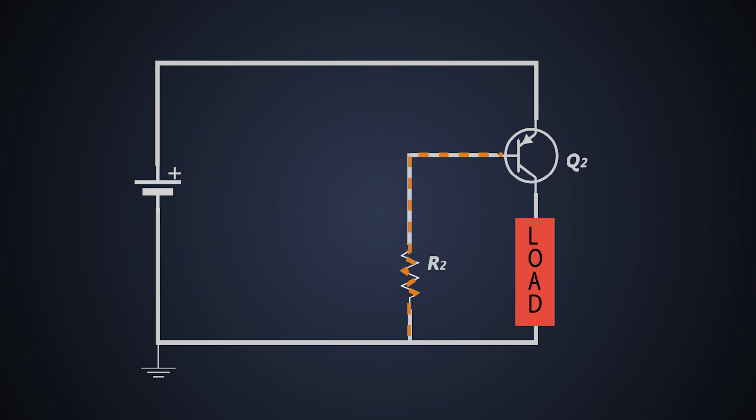Now when the voltage exceeds, this transistor has to shut down. So to turn this transistor off, we need to add one more BJT which will be connected like this in the circuit, so that when it turns on, it will pull the base of the Q2 to logic level high, that is, to the supply to turn it off. We'll name this transistor Q1.